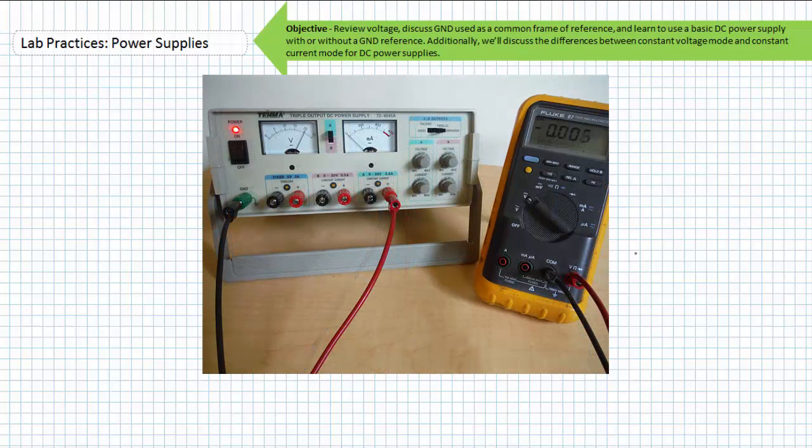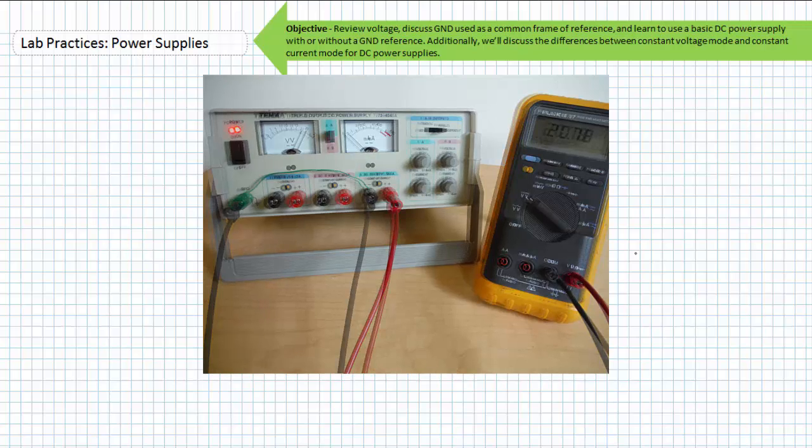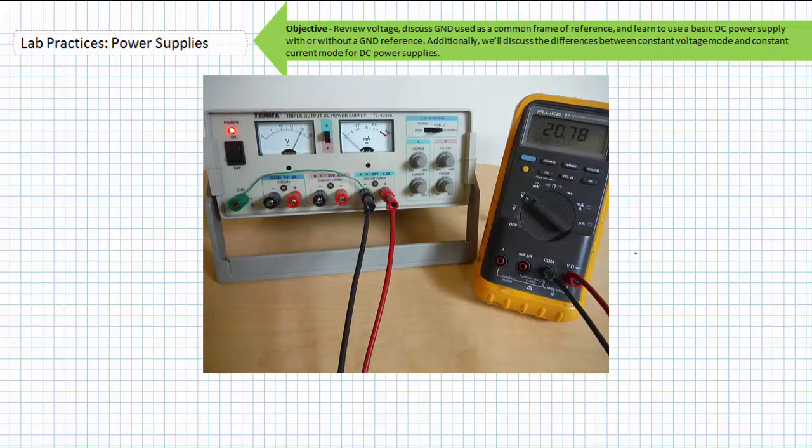Turning the power supply back on and returning to voltmeter mode, you notice the voltage between the A high lead and ground is kind of nonsense because there's no association between ground and this isolated set of terminals. In this case, the 20.78 volts of the A terminals is only with respect to each other. If, however, I tie the negative lead of the A source to ground, the positive lead is now 20.78 volts higher than ground. Again, the difference between the two terminals still exists. It's just that they're now referenced from something else.